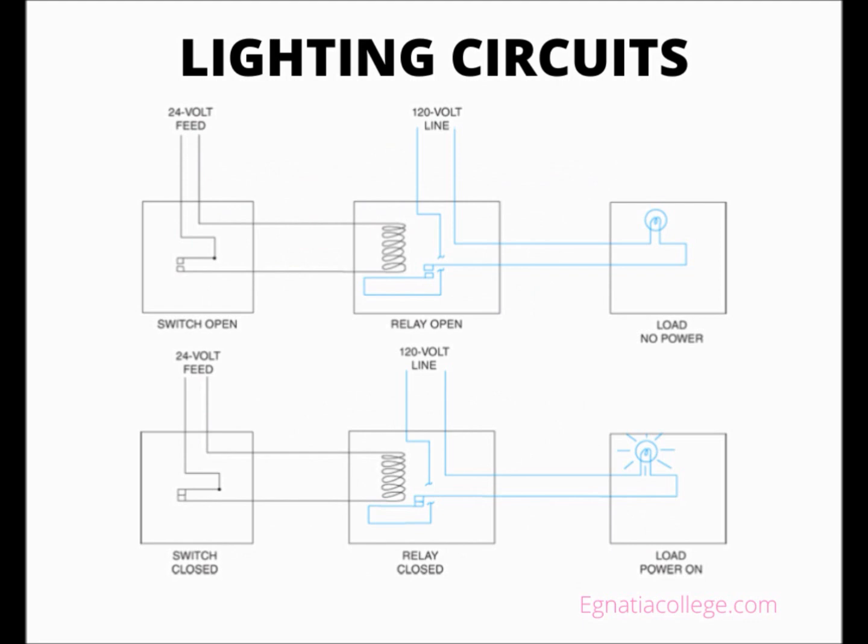A motion sensor detects any movement in the area of the sensor. So in a room controlled by a motion sensor, if there is no movement in the room for a period of time, the sensor opens its contacts, like turning a switch off. A motion detector can be used together with a switch, so that the lights are controlled normally by the switch. But if someone forgets to turn the lights off, the motion detector will.